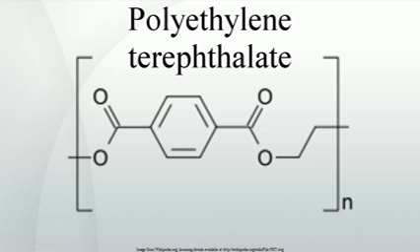Impurities and material defects. The number of possible impurities and material defects that accumulate in the polymeric material is increasing permanently, both when processing and when using polymers, taking into account a growing service lifetime, growing final applications and repeated recycling. As far as recycled PET bottles are concerned, the defects mentioned can be sorted into the following groups. Reactive polyester OH or COOH end groups are transformed into dead or non-reactive end groups, for example formation of vinyl ester end groups through dehydration or decarboxylation of terephthalic acid, and reaction of the OH or COOH end groups with monofunctional degradation products like monocarboxylic acids or alcohols.